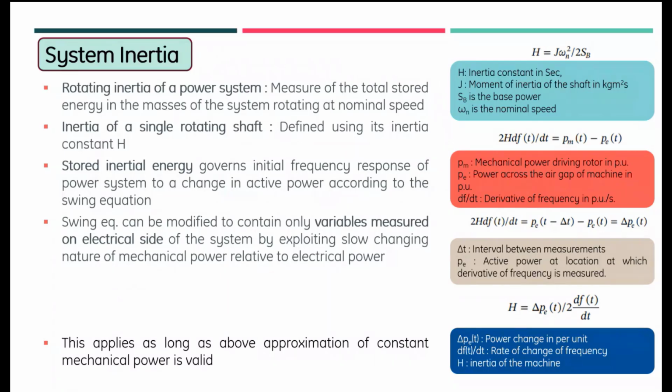If you have that, then you can estimate the regional inertia of that area. Like the combined inertia of the system, you can also estimate a local regional inertia. So let me just give you an example. Let us say one particular power system A is connected to power system B through two transmission lines. A has its own generation, and B has its own generation and load.